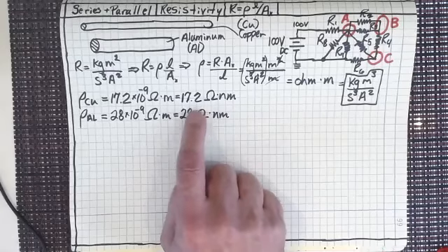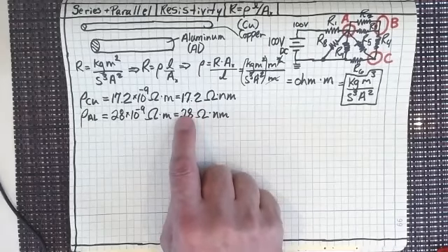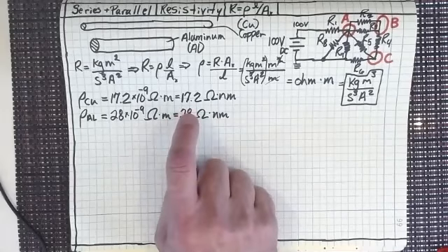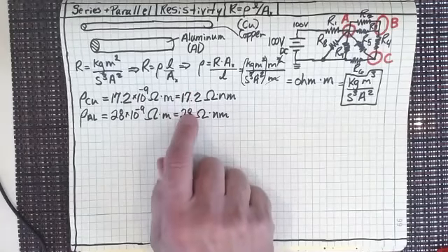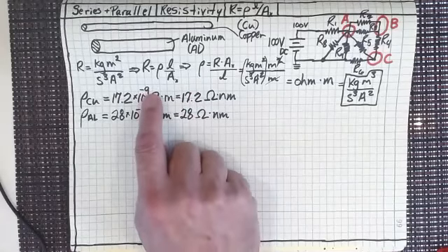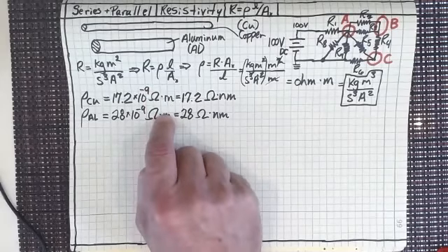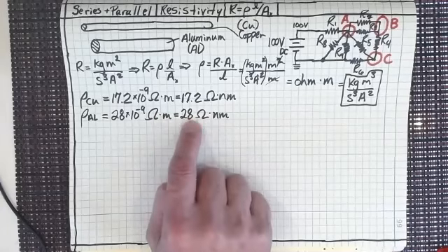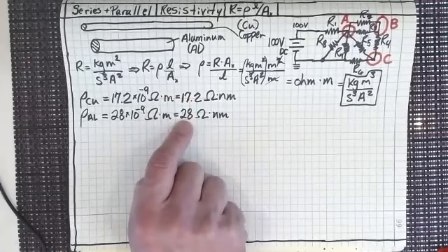But what they found out was that the aluminum oxidized too quickly, and then the center connector wouldn't work, and it just gave really bad connections.